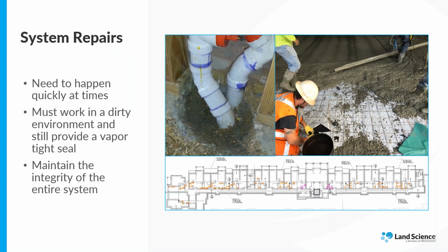So to touch on sequencing for repairs, if the concrete is already poured, the tape system will likely never be able to reseal. Repairs prior to concrete pour or leaving blockouts are extremely easy to complete. We have detailed drawings for the installers to be able to follow, ensuring that they use the appropriate layering. Post-pour, well, those are a little bit more difficult, simply because the installer does need to be more involved to ensure that they have enough barrier material available to get the correct overlap.